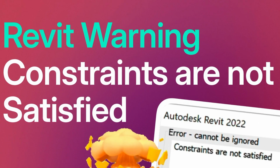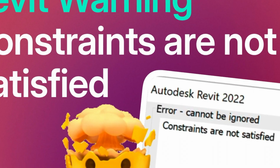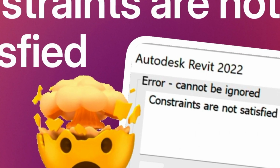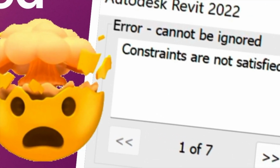Today we're looking at Revit warnings. The most common of these is the very annoying "constraints are not satisfied" error. This can flag up in pretty much any family. We'll show how to identify the geometry that's been affected and how to overcome the issue with constraints.